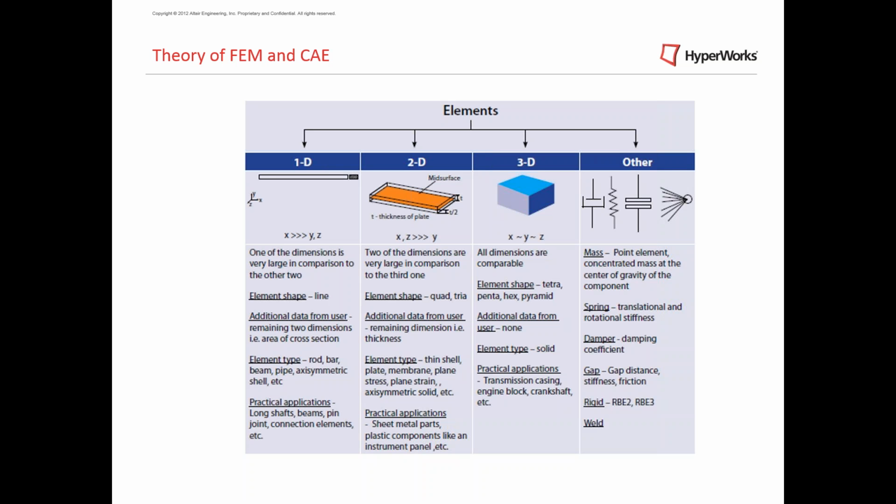3D, all dimensions are comparable. Element shape is tetra, penta, hexa, pyramid. Additional data from the user is none. Element type is solid. Practical application is transmission casing, engine block, crankshaft, etc.